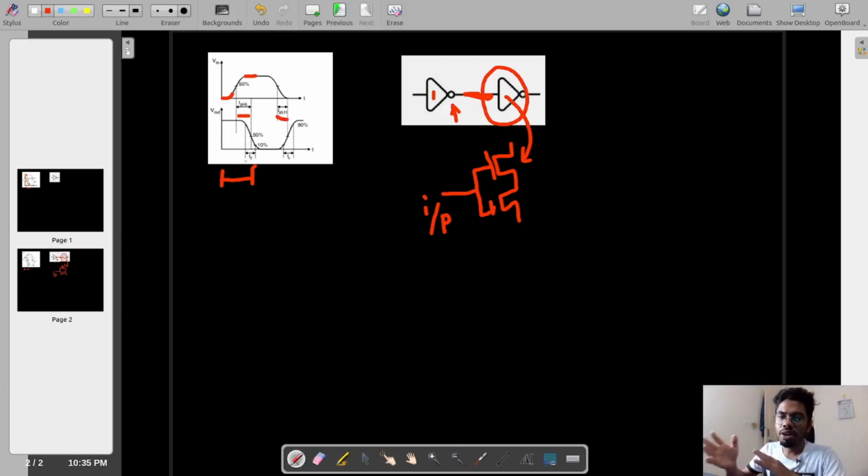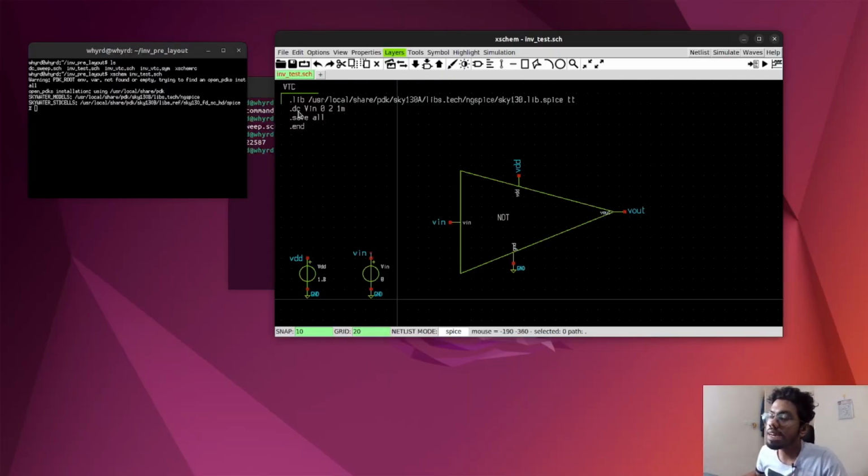So if propagation delays are all okay, great, then what are the rise time and fall time, and what is the importance of rise time and fall time? We will come to this a little later. First, let's calculate the propagation delay of our design. From the last few videos, we have already done the DC analysis, right? So now give me the answer for today's scenario. Do we need to do DC analysis, or do we need to introduce transient analysis here? And the answer is yes, we need transient analysis. Why? Because we are doing delay analysis, which depends on time, and DC doesn't have any dependency on time, right? So that's why you need to introduce the transient analysis here.